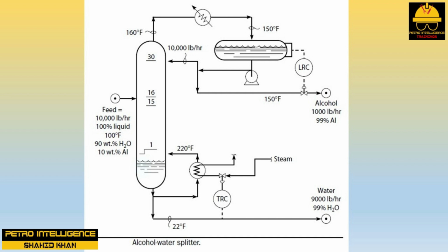Let's first look at the reboiler. As the tower top temperature shown in this picture goes down, more of the lighter, lower boiling point alcohol is refluxed down the tower. The tower bottom temperature begins to drop, and the steam flow to the reboiler is automatically increased by the action of the temperature recorder controller, TRC. As the steam flow to the reboiler increases, so does the reboiler duty, or energy injected into the tower in the form of heat. Almost all the reboiler heat or duty is converted to vaporization. The increased vapor leaving the reboiler then bubbles up through the trays, and hence the flow of vapor is seen to increase as the reflux rate is raised.